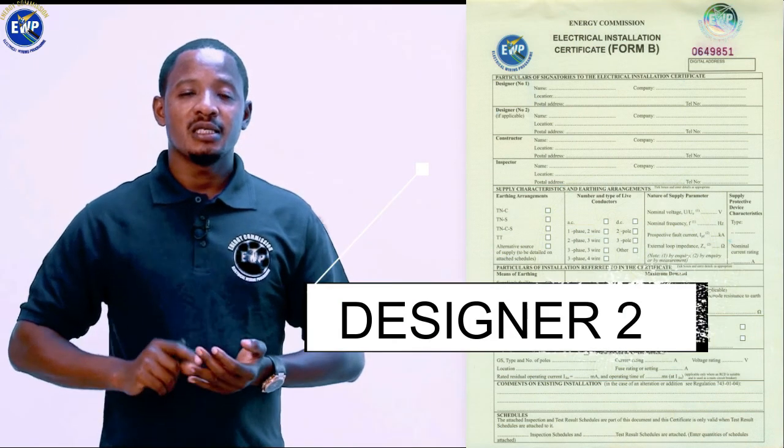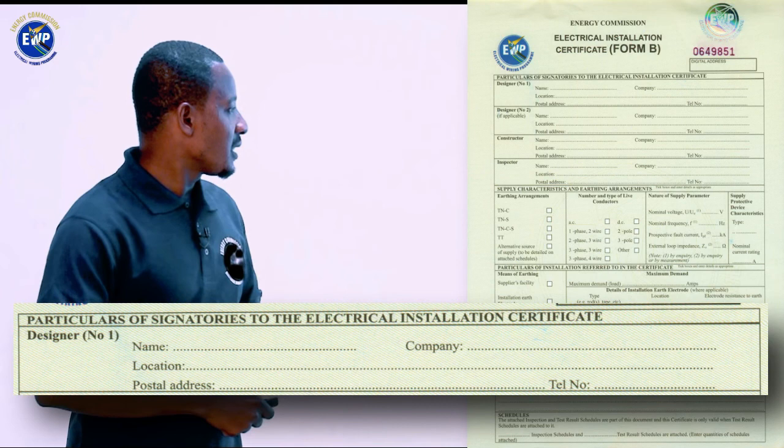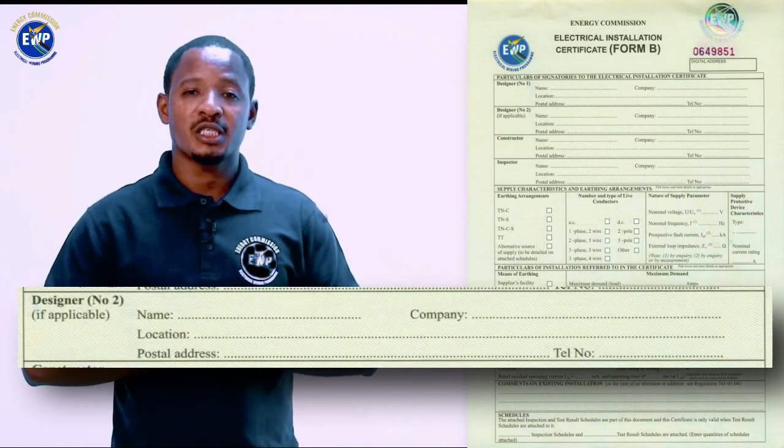On Form B, particulars of the signatories to the electrical wiring certificates include Designer 1, Designer 2, the constructor, and the inspector. Now, on Form B, the designer is expected to write his name, the company he represents, the location of his company, his postal address, and then his contact number. It is possible, for a very complex electrical installation, that there may be more than one designer. The other designer is also required to fill his portion accordingly.